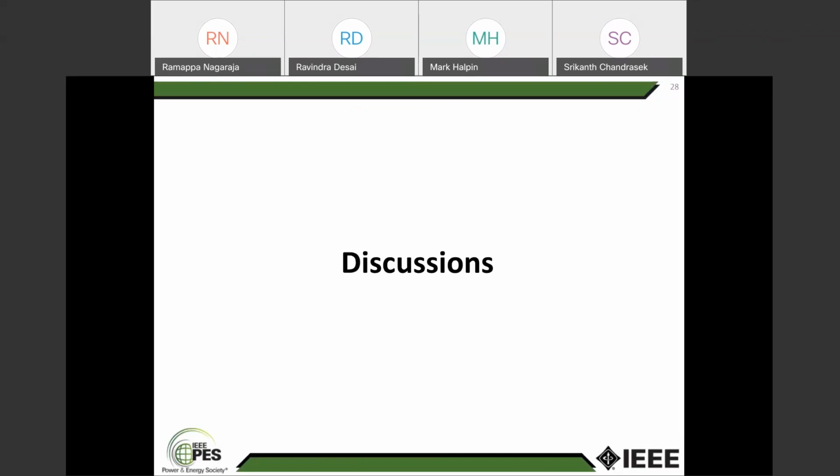Normally, these type of studies are done whenever you want to plan the SVC or the STATCOM in the system, or whenever you want to design the capacitor bank in the system. You would like to see that in the system there is no resonance point where the entire harmonic current in the grid is being absorbed by the capacitor bank. Therefore, using these simulation studies we will be able to conduct various studies and see how the system is going to perform.